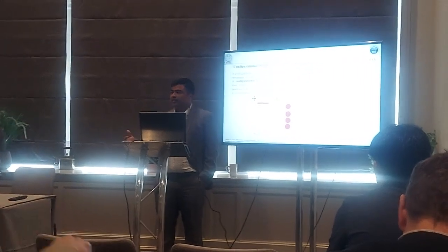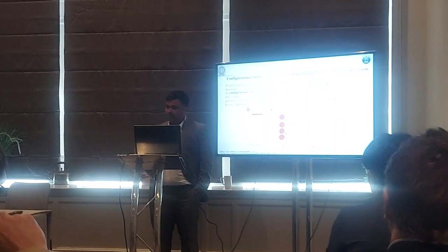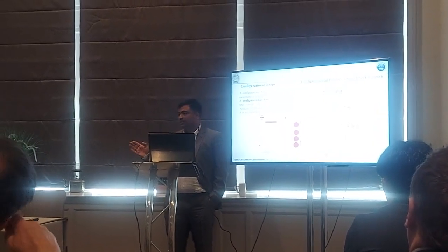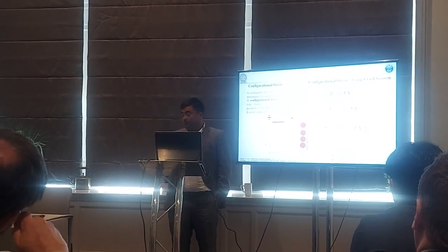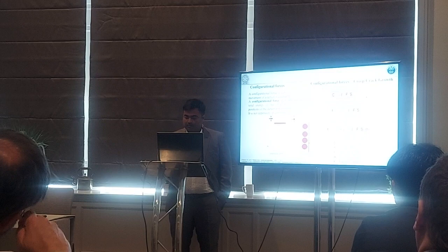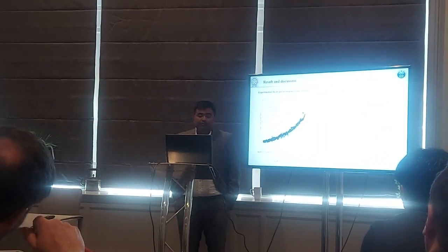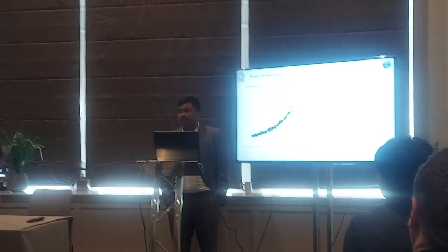Basically we are taking the configurational forces around all the sample, and we are projecting in the particular direction. By taking the projection in the desired crack growth direction, we find out the crack growth driving force in that particular direction.